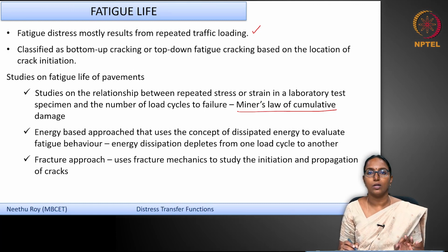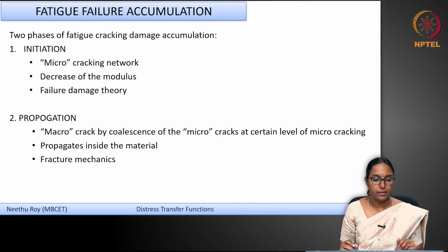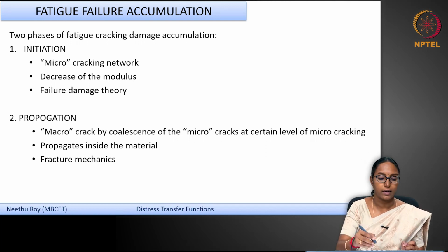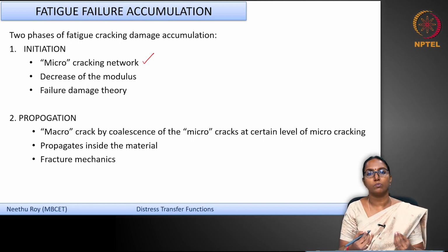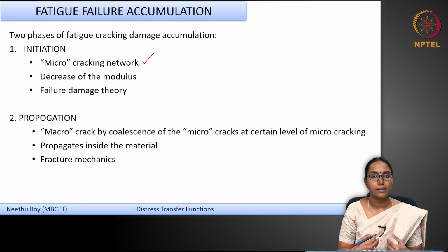Now, the third one is called the fracture approach. You can use fracture mechanics to study the initiation and progression of cracks. Now, what is this initiation and progression of crack? See, as I said, fatigue cracking or the damage due to repeated fatigue loading does not happen all of a sudden. Your bituminous mixture has certain voids. Now, these voids, when they become interconnected, can form micro cracking networks. So, small cracks will develop due to this fatigue loading, and they form a micro cracking network. This can cause a decrease in the modulus value of the material, okay.